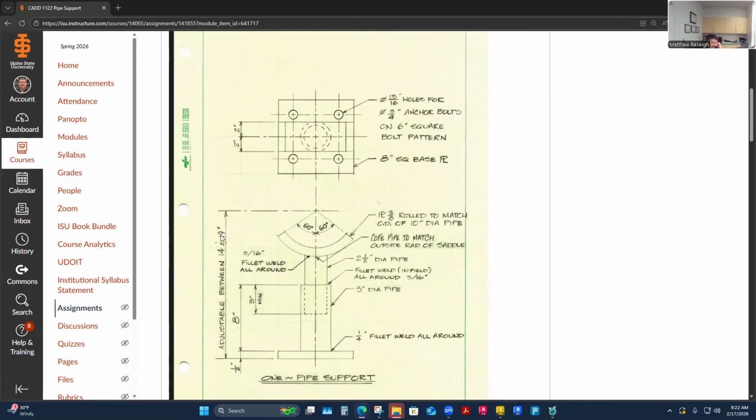I'm going to target 19 inches tall, and then plan on this part being definitely a hard length, right? This is going to be an 8-inch length of 3-inch pipe, I should say, and then a half inch. So that's going to be a fixed dimension, 8.5 to there. This is my variable. And this would be pretty common in telescoping parts.